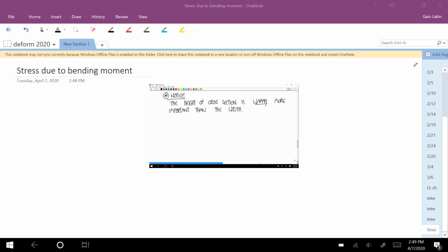So let me give you the formulas for area moments of inertia for the shapes that are likely to come up: a rectangle, a circular shape, and a triangular shape. Remember that these are the cross-sectional shapes. So for simple shapes, when I draw a rectangle, you have to imagine that the long axis of the beam is going perpendicular to that cross-section that I'm drawing. So, okay. Area moments of inertia. The first one is a rectangle. This is the one we just calculated.